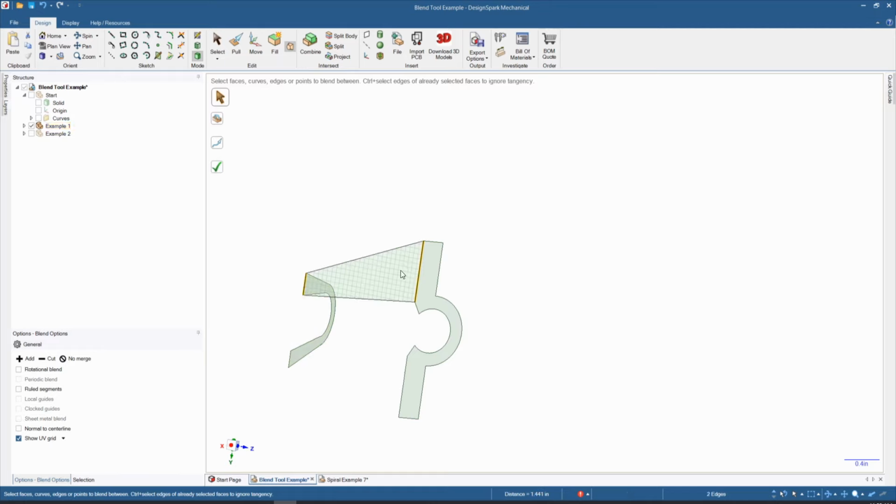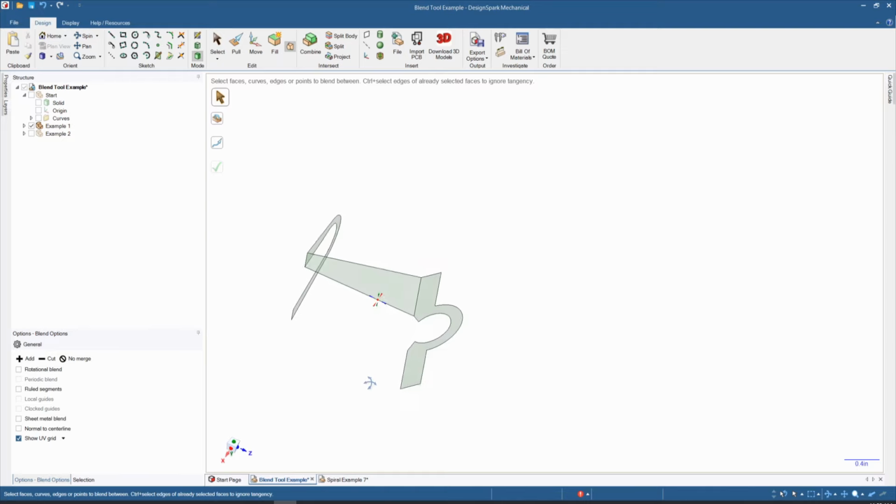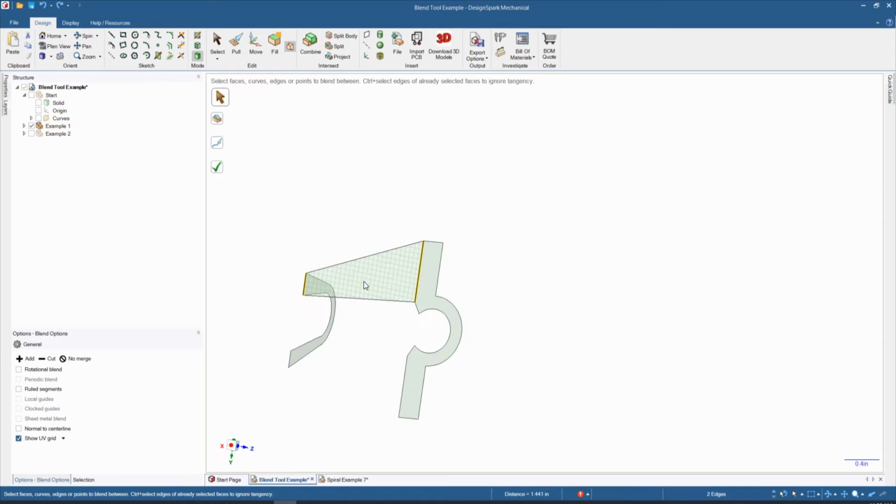those two edges. And it's back to either selecting the checkbox or hitting enter to set that in as a surface. Now that we've got this started, we can go around one segment at a time and we can select which edges we want to blend together. Now that we're doing one edge at a time, we are in complete control. So I can Control Z and back up out of this, and if we want to, we could select, say, this edge and this edge, and it will blend them. So now we are in control of how it blends one surface to the other.